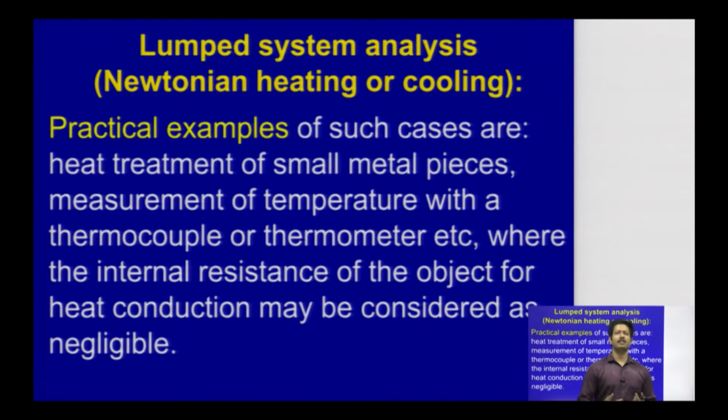Because the temperature doesn't shoot up like that. It takes some time. So definitely the temperature is a function of time. That is what we are dealing with now. Practical examples of such cases are heat treatment of small metal pieces, measurement of temperature with a thermocouple or thermometer, etc., where the internal resistance of the object to heat conduction may be considered negligible.